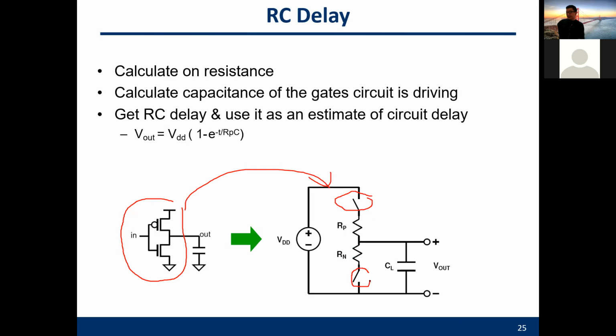These are the switches. And the two transistors also have some parasitic resistance. These are the resistances, and the parasitic capacitance. These are the capacitances. So you can analyze the latency, the resistance, the capacitance by this equivalent circuit.